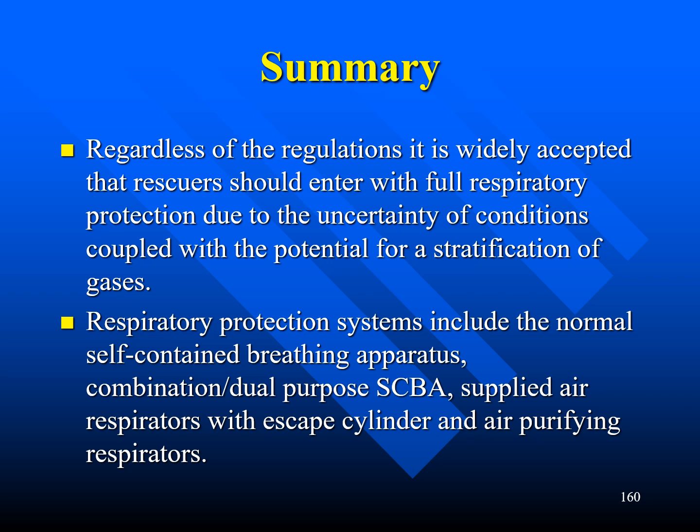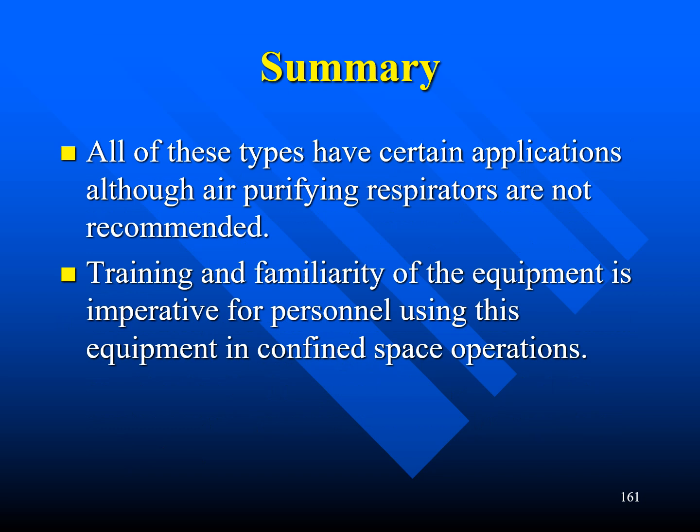Respiratory protection systems include the normal self-contained breathing apparatus, a combination dual-purpose SCBA, supplied air respirators with an escape cylinder, and air purifying respirators. All of these types have certain applications, although air purifying respirators are not recommended. Training and familiarity of the equipment is imperative for personnel using this equipment in confined space operations.